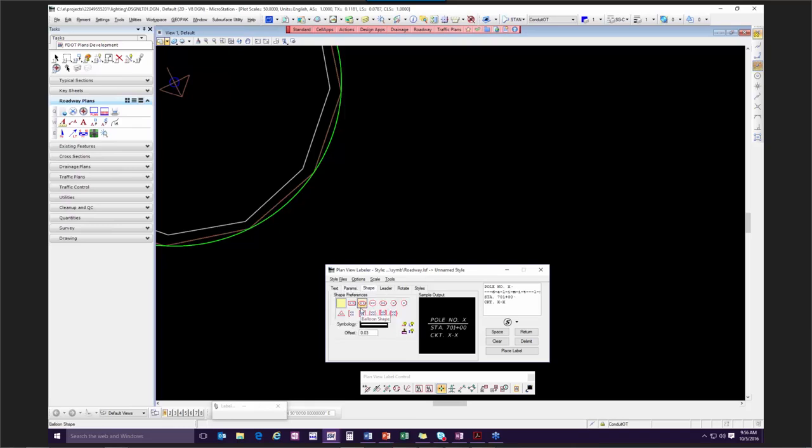I'll go to shape. My shape, I don't want a shape. I don't want to have it draw a box or anything around it. I do want a leader line. Okay, so I'm going to select 1-point leader because it's just simple. It will tag it. And I can have no terminator, or I could put basically an open or closed one, which is defined by the tool.